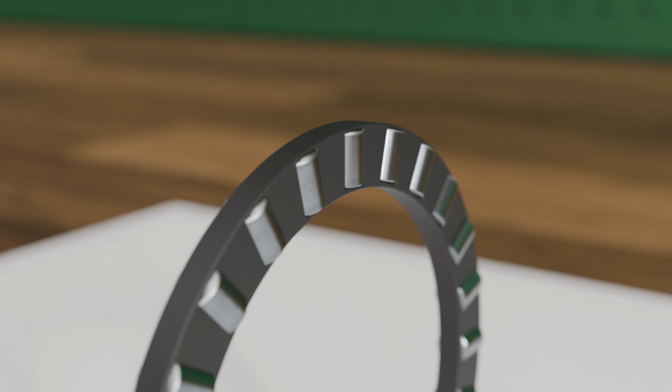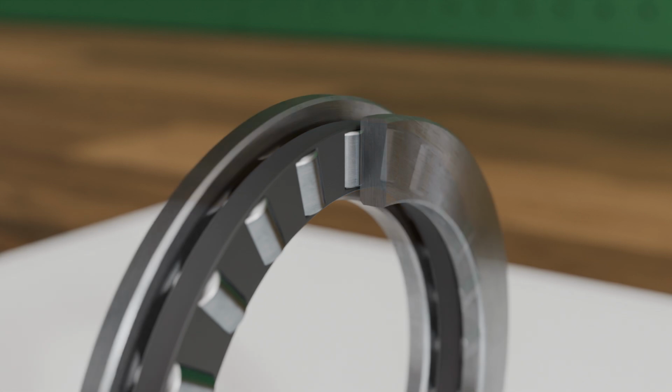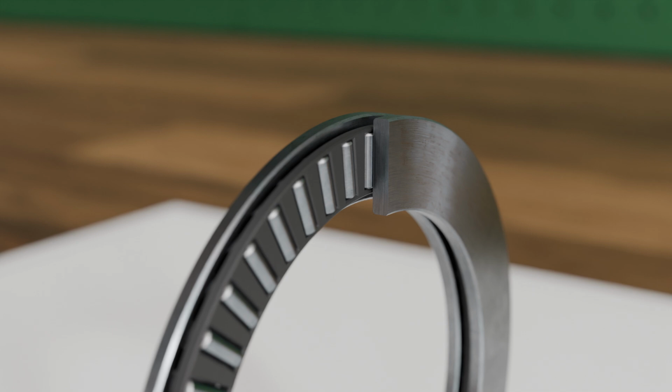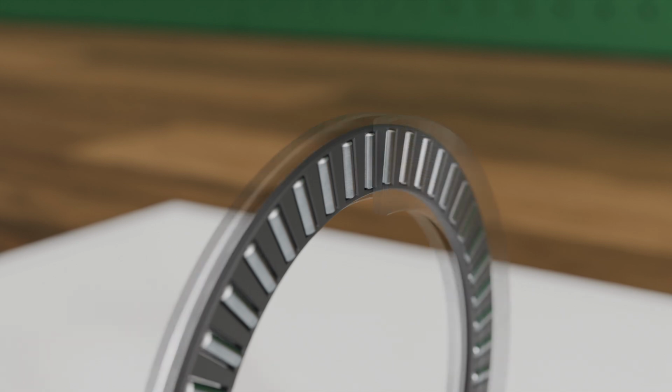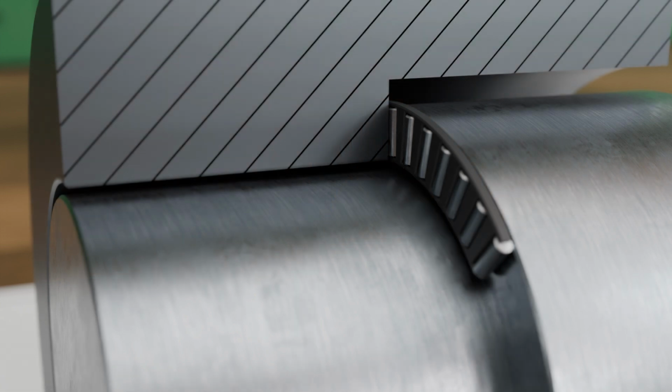However, the roller assemblies require very precisely machined counter surfaces in the housing or on the shaft shoulder. If the raceways cannot be properly ground and hardened, complete thrust cylindrical roller bearings must be used. However, to further reduce the axial installation height, much smaller rollers can be used instead of cylindrical rollers. In this case, they are referred to as thrust needle roller bearings. These bearings are also available in a version without raceway washers if the existing surfaces in the housing or on the shaft shoulder can be used directly as raceways. These are then called thrust needle roller assemblies.